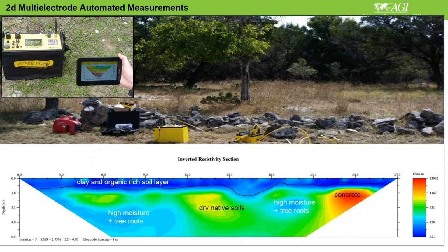If you are working in a very salty water environment, then the depth of investigation will be less. But in a more resistive environment, you will go deeper. So how can you check that? You can typically use 15% to 20% of your total cable length as the depth of investigation.